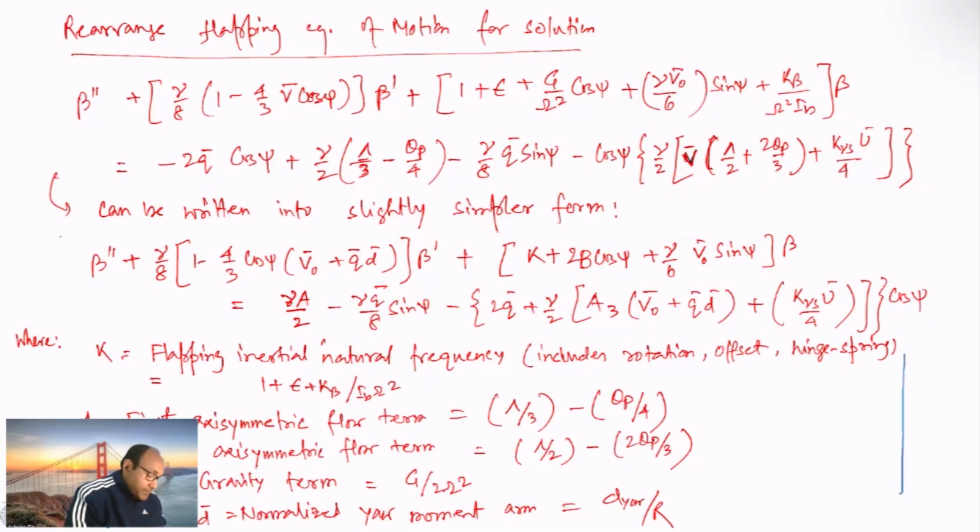All these different terms are defined here, and this is an equation which includes all of the restoring forces and moments, and this now can determine the rotor behavior under a variety of wind conditions and dynamic conditions.